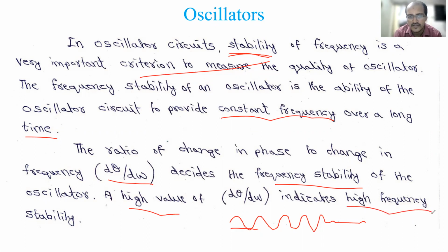So this is a brief introduction about oscillation. Barkhausen criterion we have seen. What is meant by an oscillator? An amplifier with a frequency selective network forming a positive feedback loop generates sinusoidal oscillations. That is what we call an oscillator. Then the Barkhausen criterion we have seen: the magnitude of loop gain should be equal to 1. Loop gain is defined as amplifier gain into beta factor, both multiplied and its magnitude taken. The minus sign we will neglect, and its angle should be 0 degrees. Based on this criterion we will have different types of oscillators, and we will see that also.